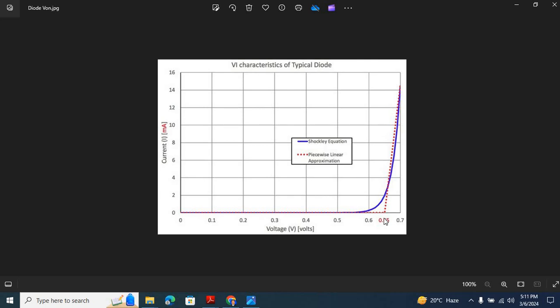Now, here is how we calculate the threshold voltage. In this IV curve, we have the maximum slope in this region. So we extend a line from the maximum slope region onto the x-axis, or we can say we determine the x-intercept of this maximum slope. And this point, the x-intercept, is called the turn-on voltage of a diode. So this is the story of the forward bias and the turn-on voltage for a diode.